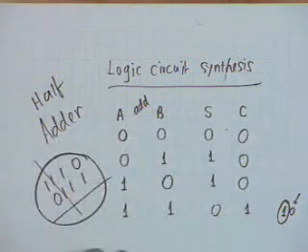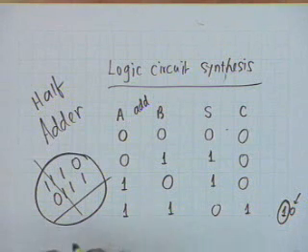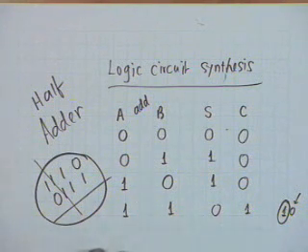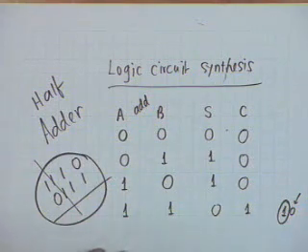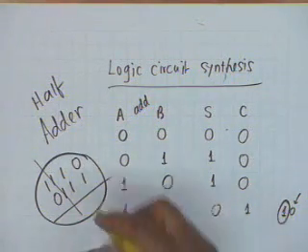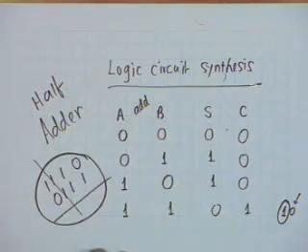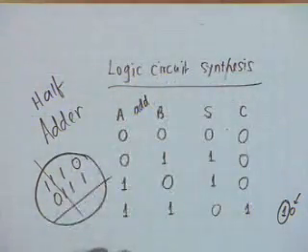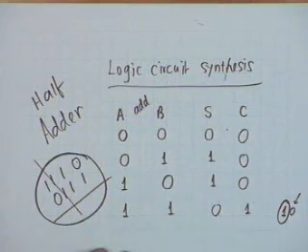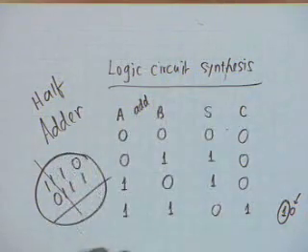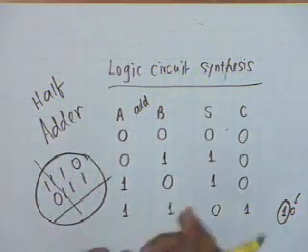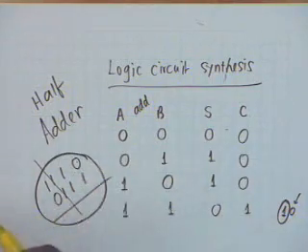So this is called a half adder, and you can appreciate that one half adder will be needed in the addition of any two binary numbers. The first digit, the rightmost digit addition, shall require a half adder because you don't have a carry from the previous addition, as there is no previous addition.